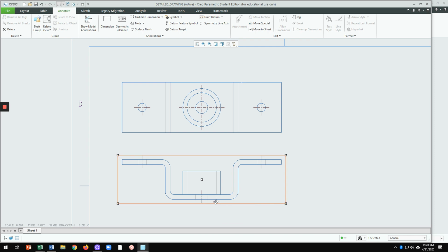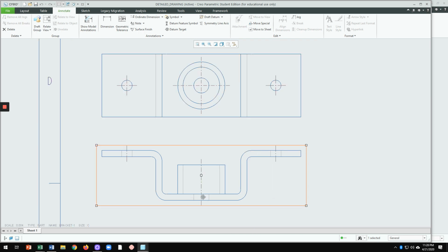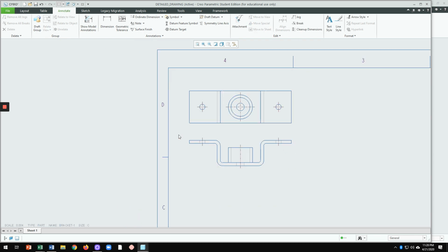But if you wanted to say this is a concentric hole, you can just click on this, and then you just stretch that center line to extend about 1/4 of an inch beyond the object line. For example, if you wanted to look at this from the print preview, you can see that these are the hidden lines, okay? Hidden lines.